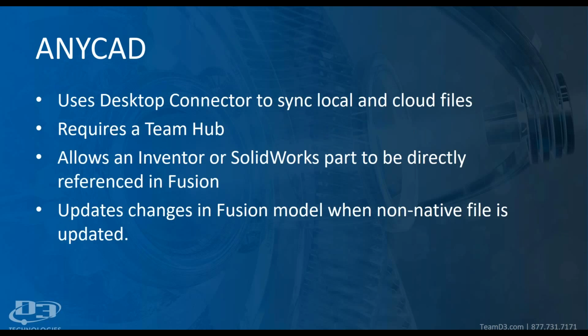All right, now the first thing about AnyCAD is you will need the desktop connector app, which allows you to synchronize local and cloud files using your hard drive and Fusion, or excuse me, and A360. If you are using Fusion, you have to activate your preview, and you will need to have a team hub in order to take full advantage of AnyCAD. At this time, it allows you to use Inventor and SolidWorks parts, and they can be directly referenced inside of Fusion.